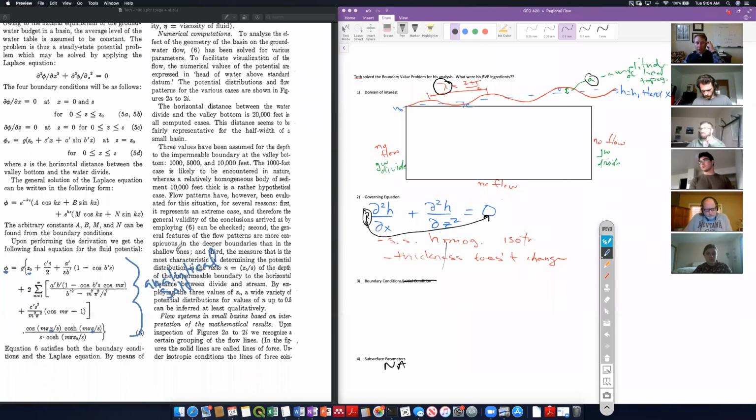So these analytical solutions are gold. They give us head at any place in our domain, all right? And allow us to solve for the groundwater flow, but we can only derive analytical solutions for very specific cases and simplified cases. So in this case, it works because we were steady state and homogeneous and isotropic, all right? And we were able then to derive this analytical solution, but you can see that even for this very simple system, our analytical solution is messy.